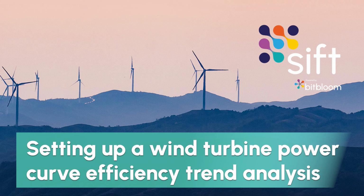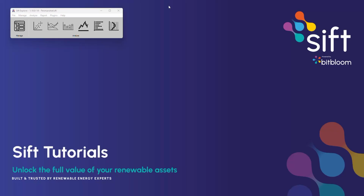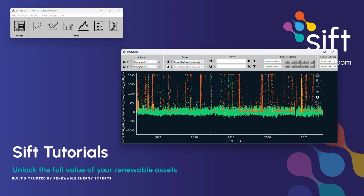We ended our last tutorial having created a residual power signal. This was calculated as the difference between measured power and an expected power calculated using historic operational data. In this video, we will set up an analysis with these power residuals to monitor turbine power curve efficiency over time. Let's create a KPI.